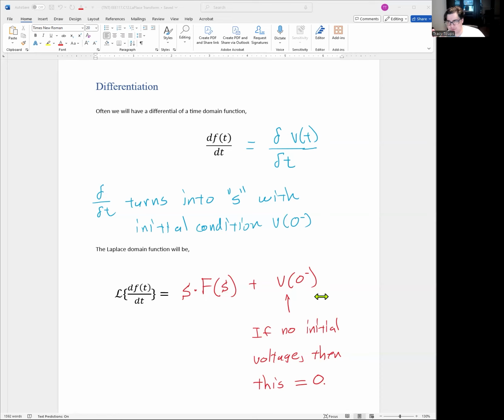But that's all integrals and derivatives. You've got to find initial conditions, right? What is an initial condition? What if the capacitor is already charged before we observe the circuit? What if the capacitors or inductors are pre-charged? This could have happened yesterday before you looked at it. If the capacitor is already charged, we don't have to charge it. That obviously changes the circuit parameters, right? So that extra voltage on the capacitor, we have to take into account.